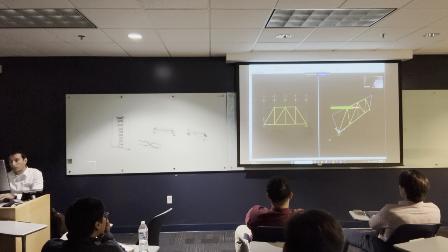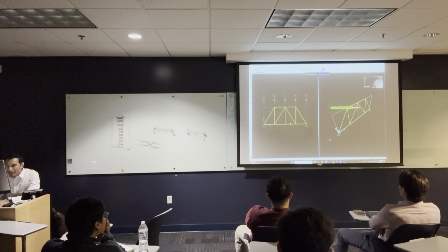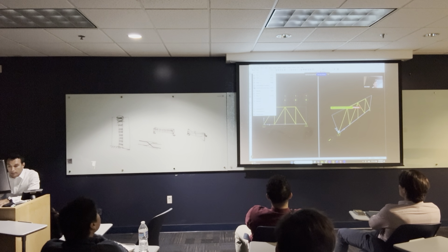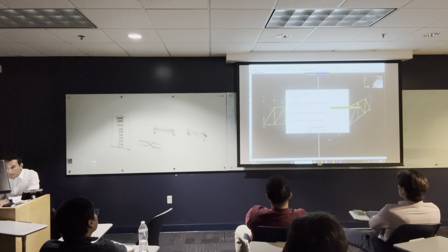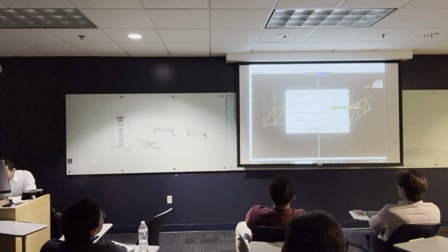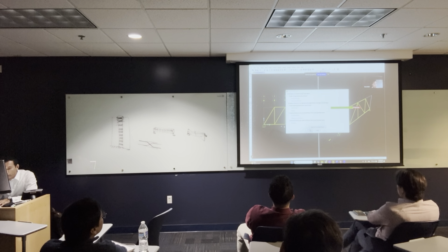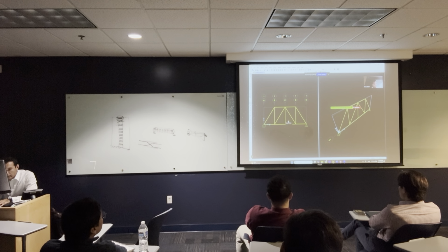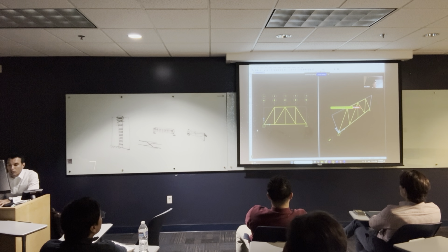F4 basically shows the undeformed shape, or you can click on this one. And I'm gonna click on this frame and these 3 points, and I'm gonna say Edit, Lines, Divide Frames. And I'm gonna say break at the intersection with the joints. So it's gonna break this frame at the joints that I selected. Here, everyone is gonna be separate. And I have to do the assign again.